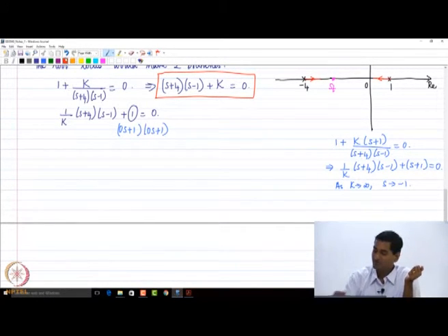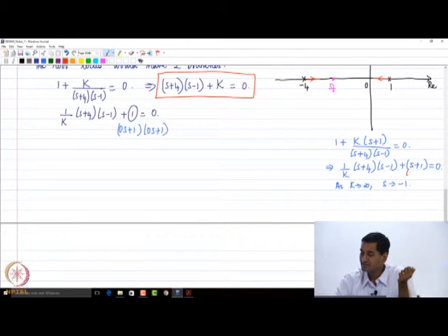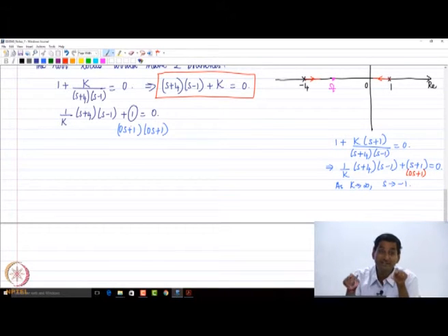So, the way people will demonstrate it, without going through the proof and so on, is that let us say we multiply this with 0 s plus 1, the product remains the same. It is as if you make the number of terms to be equal, and you see that s tending to infinity is another root. Okay, that is what happens here, right. So, what I did was that I replaced this 1 with 0 s plus 1 and 0 s plus 1. Okay. So, 0 being, right, or if you do not prefer 0, you put epsilon tending to 0, because we are looking at the limit analysis, right.